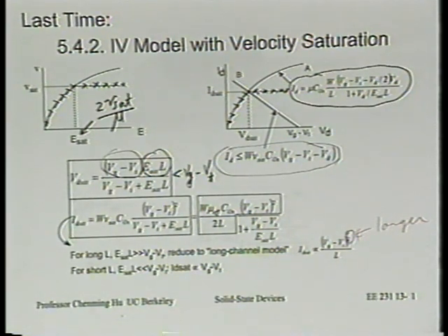Now that alone is an interesting fact, because a lot of the design, of course, low power design. I don't mean low power physical design. I'm particularly thinking about analog circuits, where you bias the transistor really at only Vg equal to Vt plus 100 millivolt. So in that case, the transistor does behave just like a long channel transistor, and that's a fortuitous thing, because designers often still like to use this parabolic relationship between current and Vg and make a lot of design considerations based on those simple models. It happens to work.